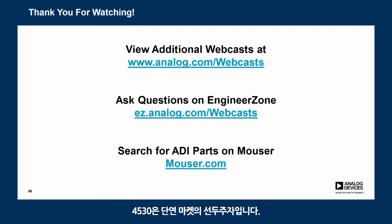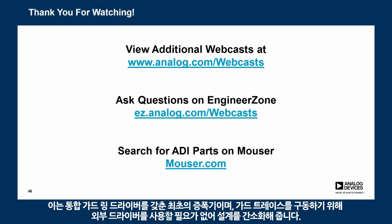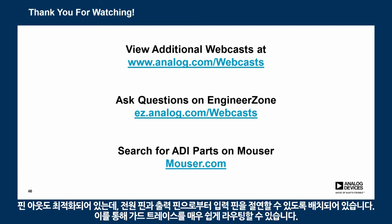Definitely the 4530 is the market leader. It is the first amplifier that has an integrated guard ring driver. It simplifies the design, and it eliminates the need for you to go source an external driver to drive the guard traces. And its pinouts are optimized. They're positioned in a way that you can isolate the input pins from the supply pins and the output pins, and it allows very easy routing of your guard traces.